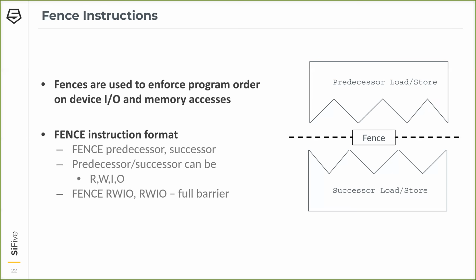RISC-V also implements fence instructions. Fences are used to enforce a program order on device I/O and memory accesses. That is, all operations that happen prior to the fence are guaranteed to complete prior to the operations after the fence.